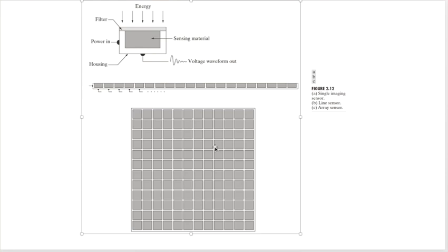But not only that, every one of these transistors, every time you have a PN junction, when a photon hits it, right? So if I take, everybody know what a PN junction is? Yes? Right? Okay. So when I have a PN junction, if I take that junction and I reverse bias it, what happens? Does current flow or not flow if I reverse bias? It does not, right?